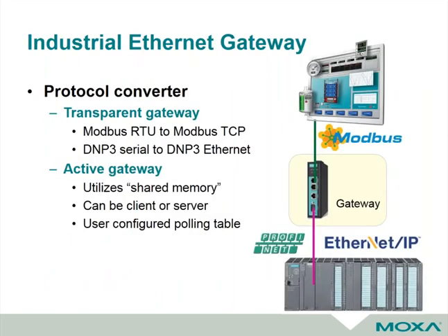If you have to bridge protocols, please remember there are some great devices out there that eliminate the need to use an industrial PC for this, and eliminate the need for expensive plug-in modules that go into a PLC. We've got a lot of folks that like to use these with variable frequency drives. It can be less expensive to use a single gateway than to have to put communications adapters in all those VFDs. They can be transparent gateways, where you just set up a few things like your IP address and your communication speed on the serial side, and that works really great for Modbus and DNP3.